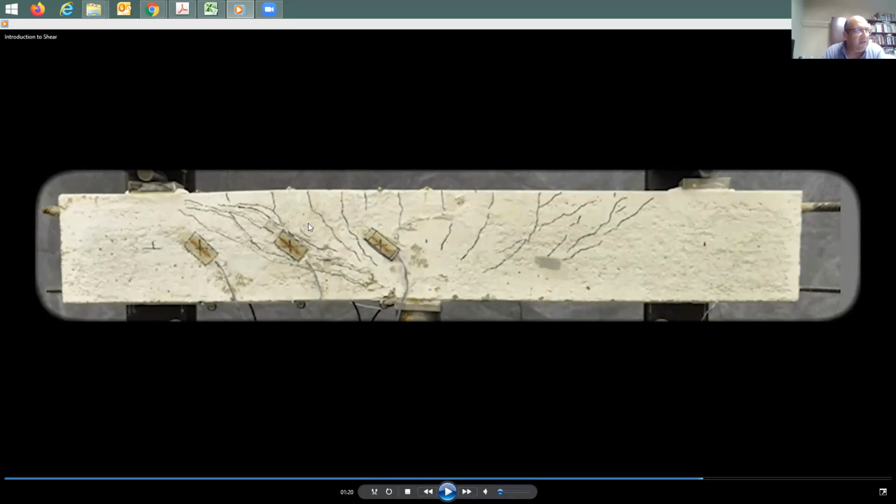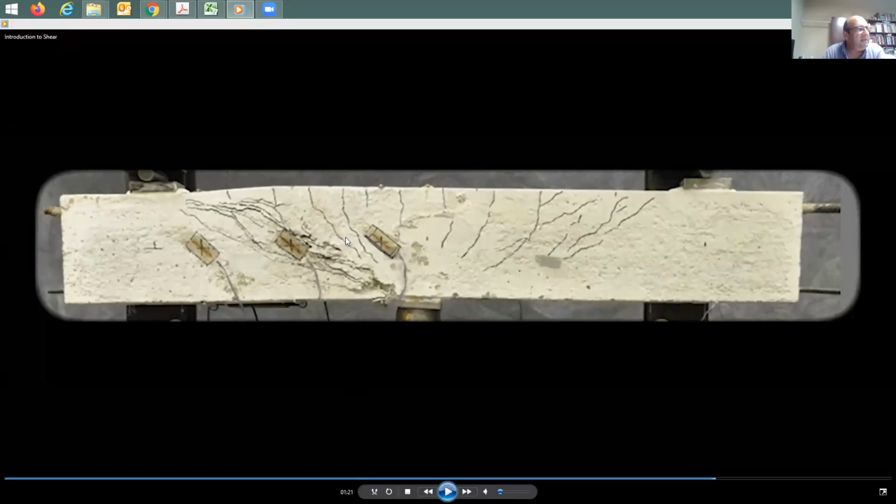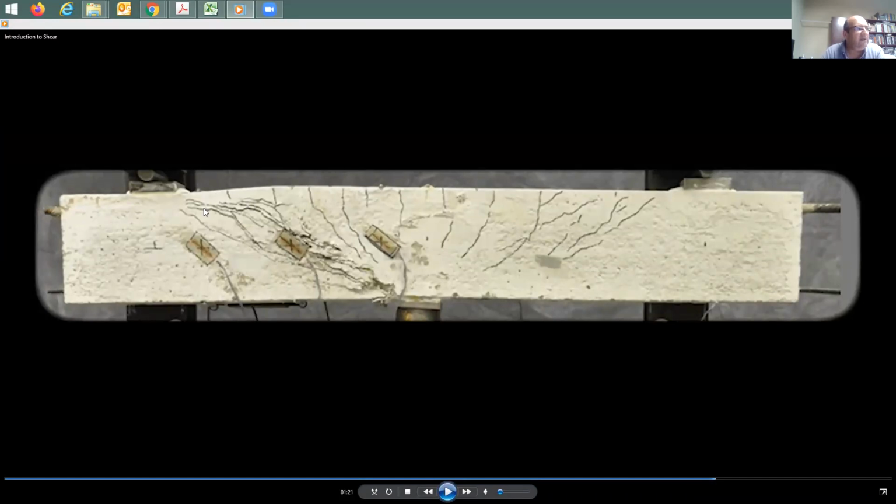So this is actually the diagonal tension I was just talking about, and this is going to be the shear crack. Look what happened. You see this? This is not deflection. This is just failure. Failure started already, and you don't have enough warning. But the rebars are still there, which means this beam is strong in flexure, in moment, but it is weak in shear. Now we understand why we say ties can resist shear, because what's needed to keep these two pieces together is just to put vertical ties here, right? If you have enough vertical ties, these two pieces act as one piece. So this beam lost its integrity because you don't have enough shear ties.